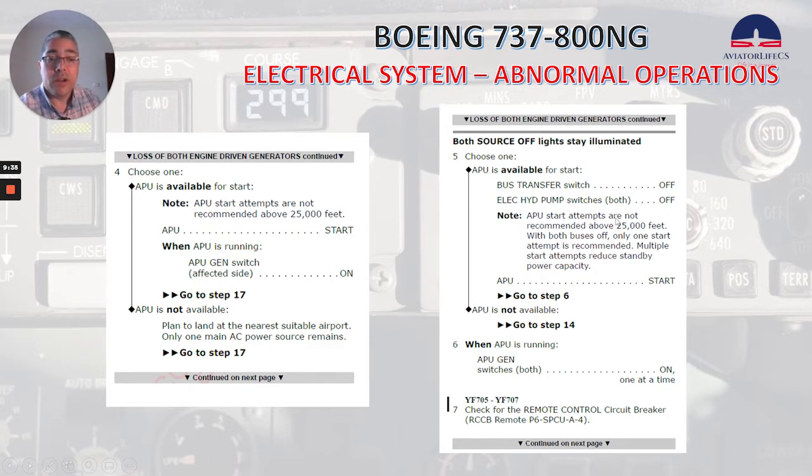Note, APU start attempts are not recommended above 25,000 feet. With both buses off, only one start attempt is recommended. Multiple start attempts reduce standby power capacity. APU start, we'll go to step 6. APU is not available, go to step 14.